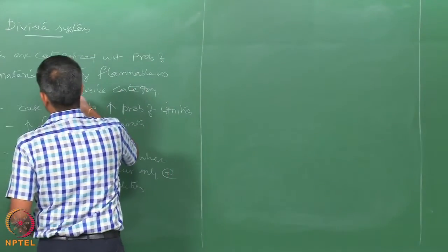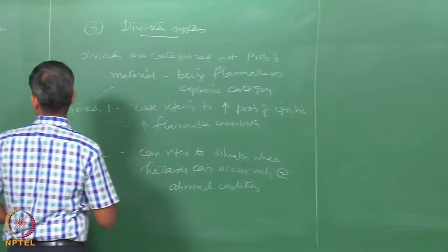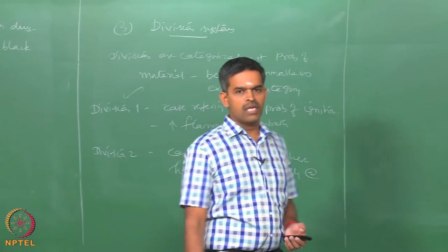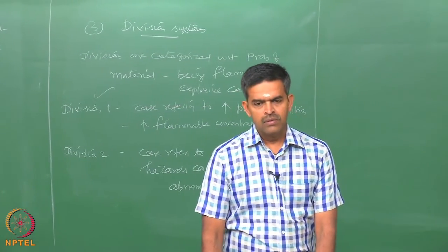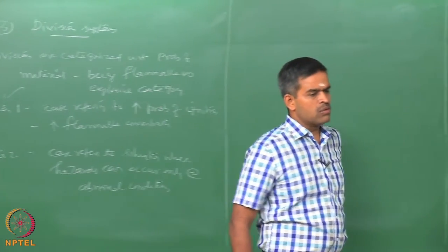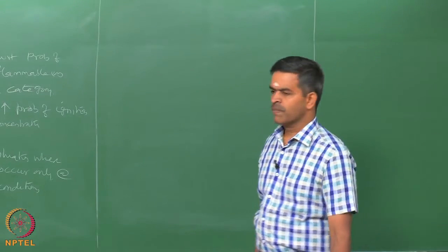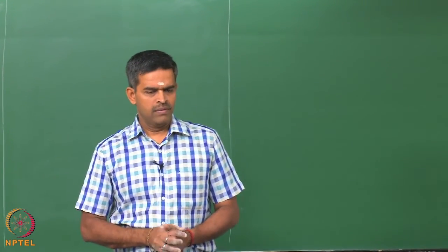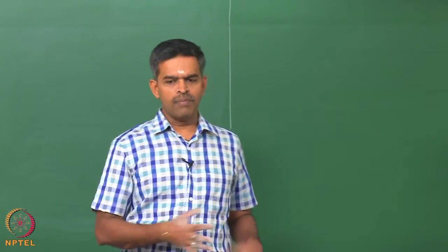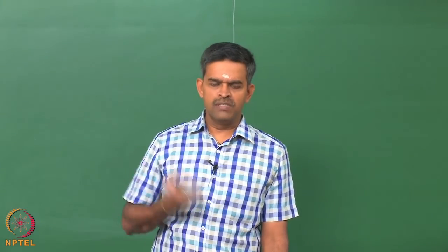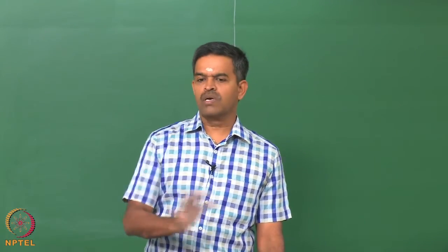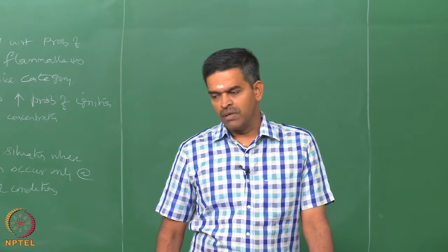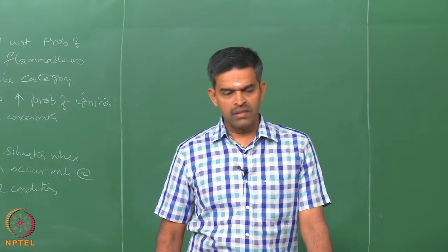So, one can look at the division of the systems, the class of the systems, and the groups of systems, which all come under one category of explosion proof systems. So, friends, in this lecture we discussed explosion protection. Essentially there are 3 or 4 systems by which this can be done. One, by inerting or purging. There are many methods by which this can be achieved, and they have been compared in terms of efficiency, speed, and economy, that is, consumption of nitrogen as an inert gas.